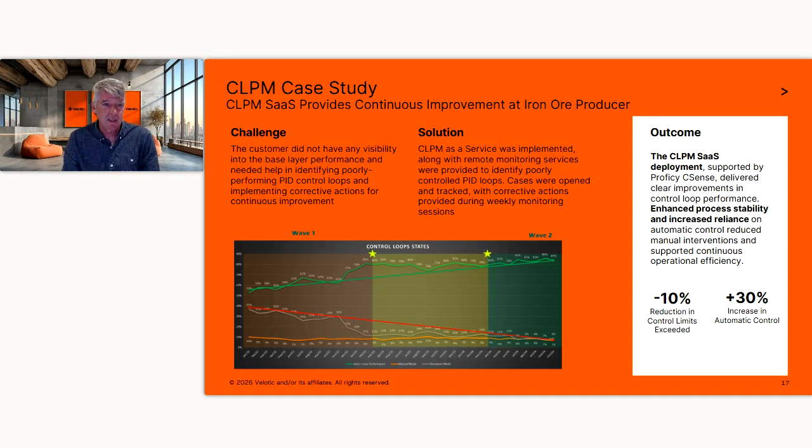Another one here that's kind of interesting is showing the status of PID loops in this factory. So they're saying in wave 1 here, what they actually had is auto or performance mode, right? So it's starting at about 55%, but also this machine was in shutdown mode 37% of the time at the beginning. And then it was in manual mode, meaning somebody said, I'm taking this out of PID control and I'm going to manually adjust things. And it was down here.